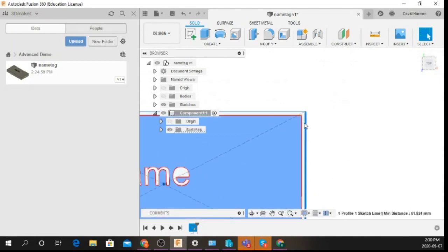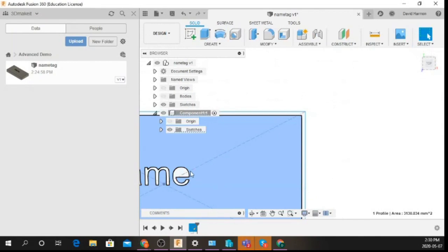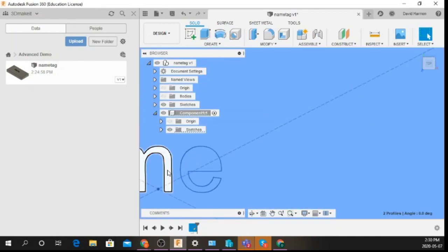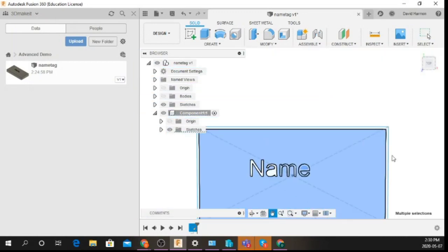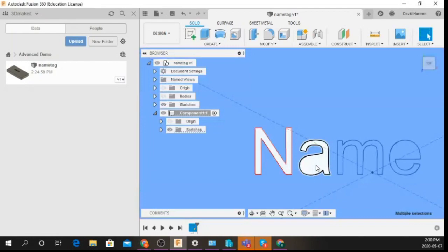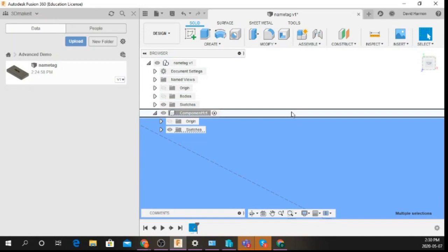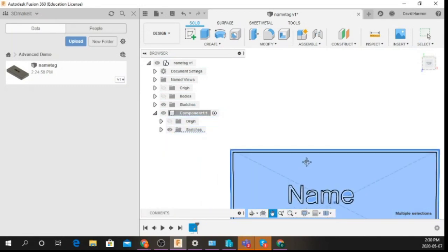So I'm just going to go in here. Now you can see here, because I used the top of the other box as a sketch plane, this part here is still showing. So I actually have to go in and this is the fun part. You've got to click all of this, which is fine. It's not too bad. It's 4 things and one on the outside. So I'm selecting all of this in my sketch, so it's blue, and then I'm just going to select this part, and that should make one solid extrusion.